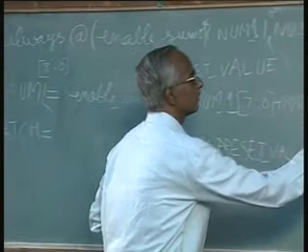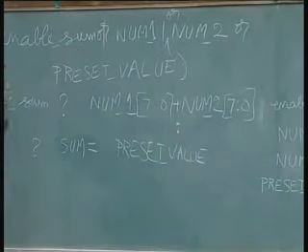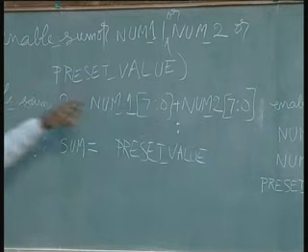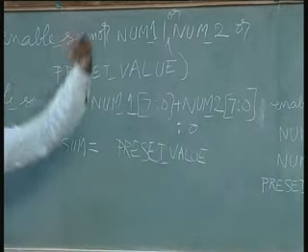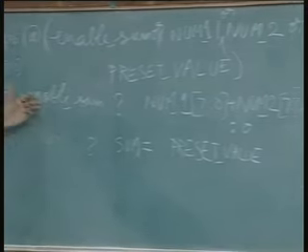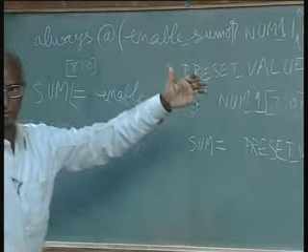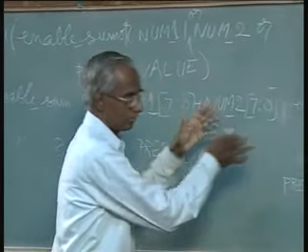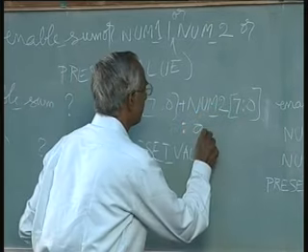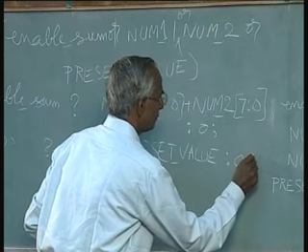So, we have forgotten another input for the mux. So, we will have to put a colon and then put just 0 at the output. If the enable is not valid, not asserted, then we need to put just 0, because we just want to make a distinction whether it has gone through the actual process or not. And similarly here we need to put 0 here.